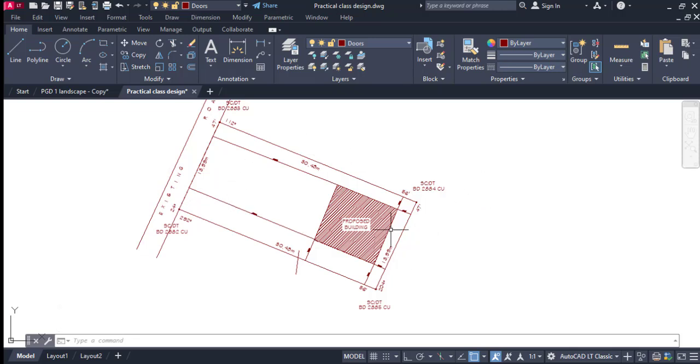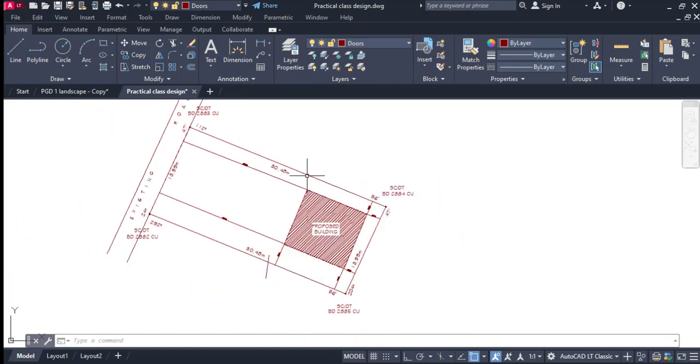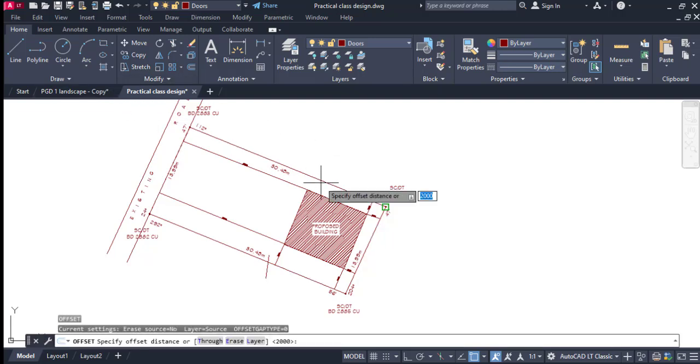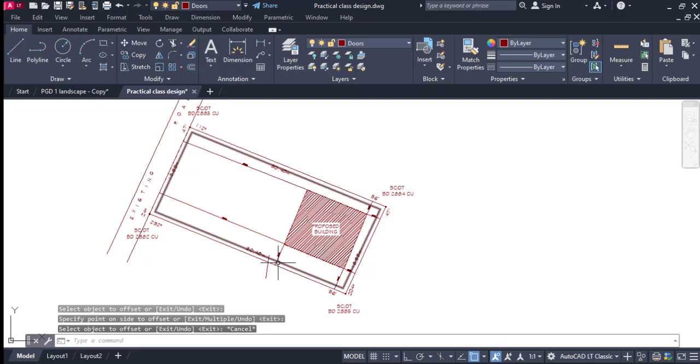Now, suppose I want to landscape this. Okay, I want to create vegetation surround and all that. So let's just say I want to create a mini design here. So I'll just offset. Let me say I'm taking my flower base to be like 600 millimeters. That's 0.6 meters, right? So 600 offset coming down here with inside.